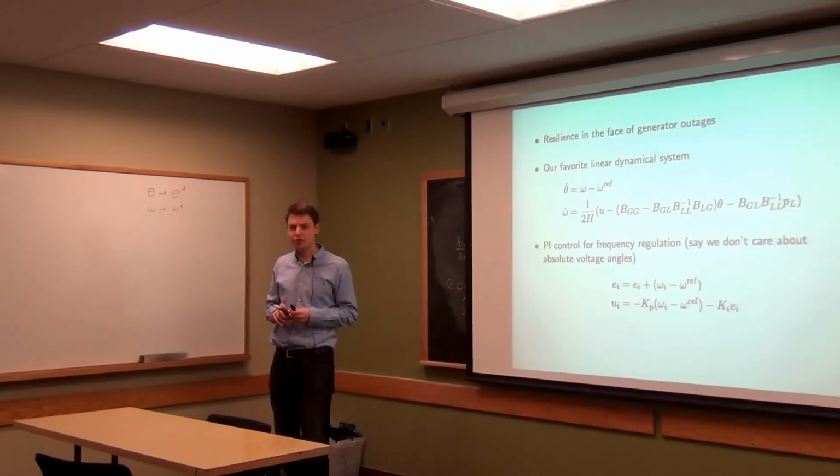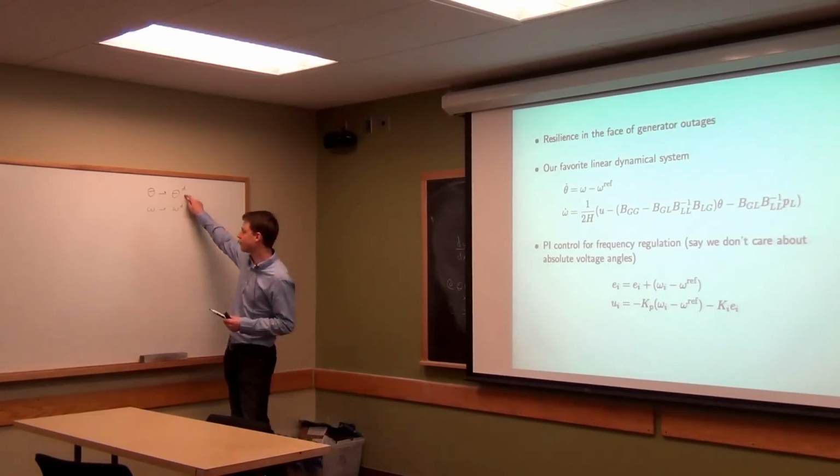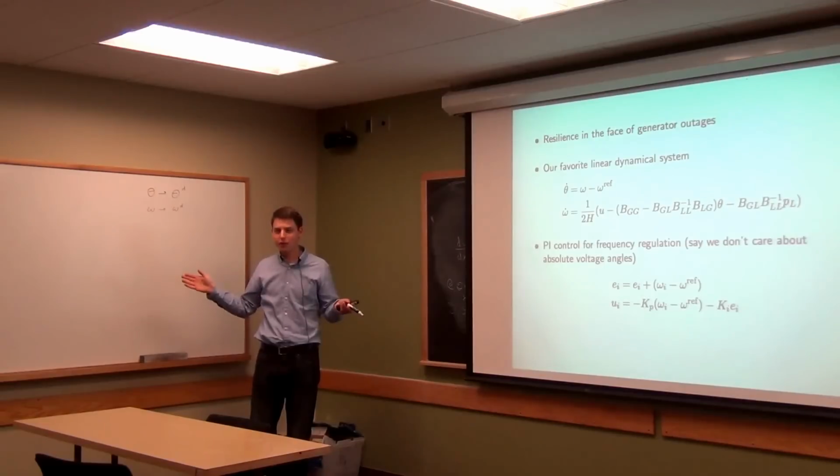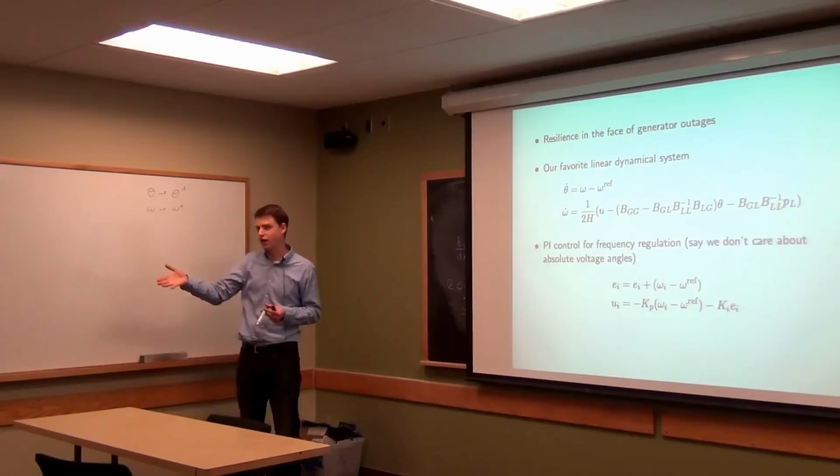And it's also easier to do this in some sense, right? Because power angles only make sense relative to each other. So in order to know your power angle, you have to synchronize to some global source. Whereas frequency, you can measure just at the source.